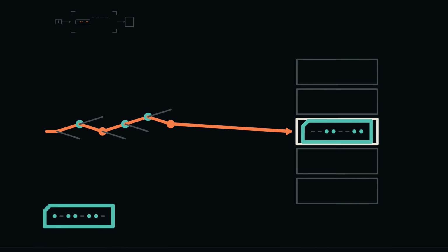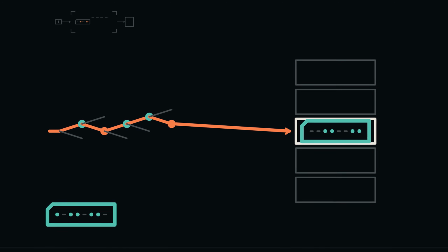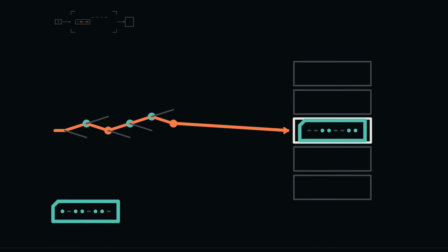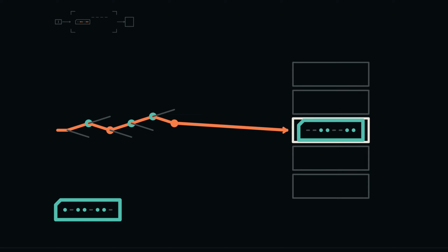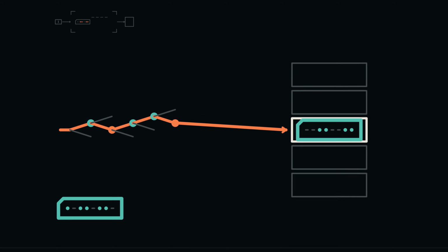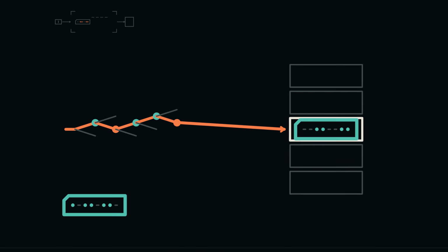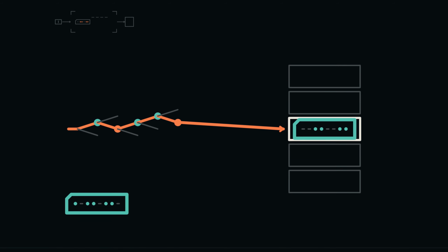Use the doubling rule before the answers appear. How many address bits are needed for 8 locations? 3, because 2 cubed is 8. For 16 locations? 4, because 2 to the 4th power is 16. For 256 locations? 8, because 2 to the 8th power is 256.